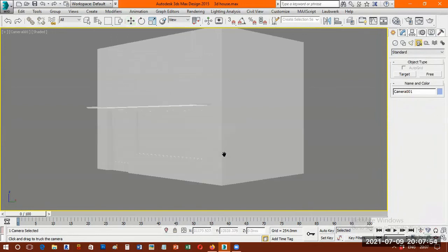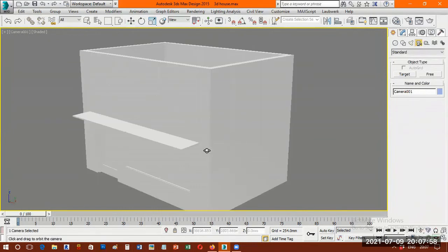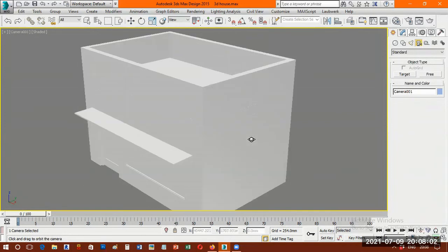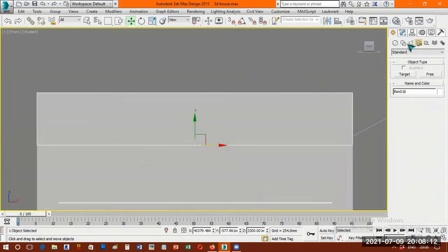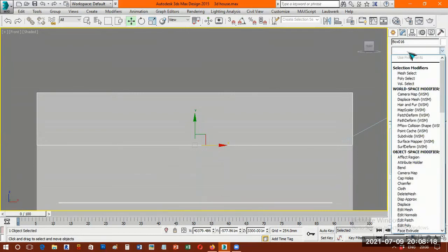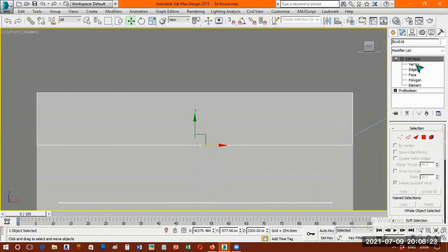Slightly drag this down. And orbit, I can do this round way like this. Orbit view slightly like this. Now, one by one, I select this. I feel the height of this parapet is too heavy. So what I'll do, I will go to front view, go to modify, go to this modifier list, press E on my keyboard, edit mesh, select this, expand this, choose a vertex.